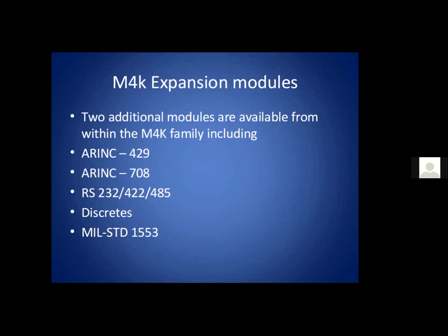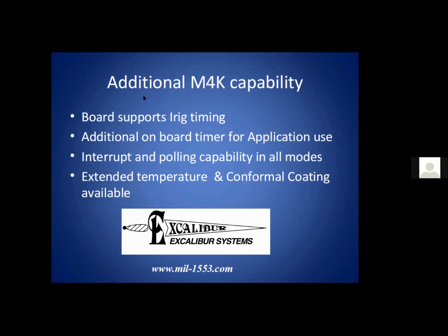But we've also got a CAN bus. Actually, let's not talk about CAN bus here. And so these modules are also available with the card. As I mentioned before, we support ARINC timing. We've got just a standard timer on the board so that if you want to know when 10 seconds has elapsed, it'll tell you, or 10 microseconds for that matter. Interrupts, polling, extended temperature conformal coating, all kinds of fun things.